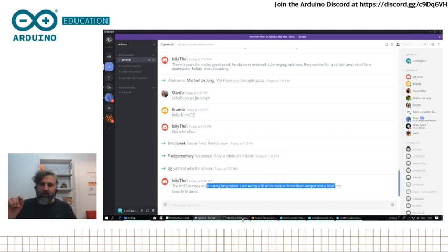So now we saw 2 different sensors. We saw our noisy friend, the very slow reacting, resistor-based temperature sensor, and then we saw the LM35, which is a silicon-based temperature sensor that is very easy to use for projects. Like if you have to make a project with students, this is super useful for doing simple data logging. What I would do if I was making a project with students, I would probably discard the decimal numbers if I was, for example, measuring room temperature, or eventually, as Billy mentioned, I would build a filter for that. So let's go to the next one.